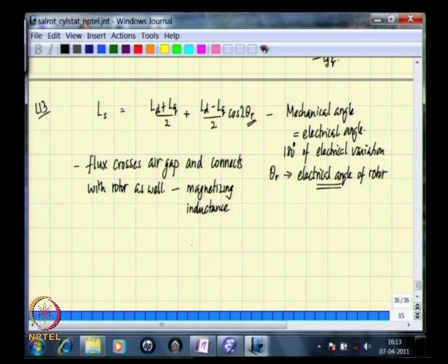In addition to this kind of flux, since the stator is essentially a cylindrical stator, and we have seen in the animation that the stator winding goes through the stator along the axis in a particular slot, and then it comes out of the stator and then travels along the circumference of the machine and then goes in through the slot 180 degrees away, and then further goes along the circumference and may make another turn.